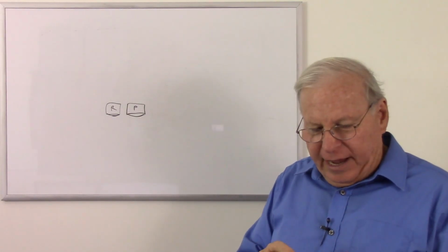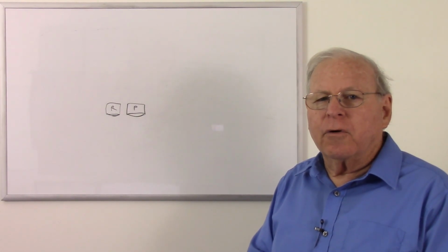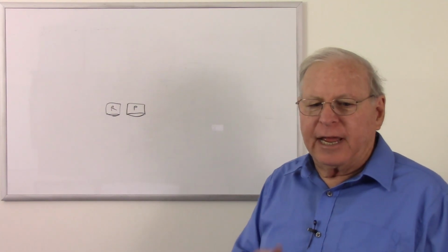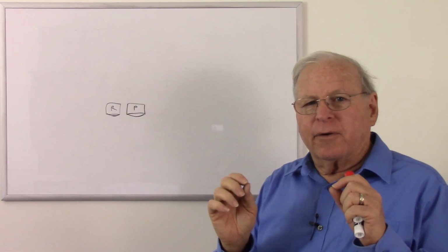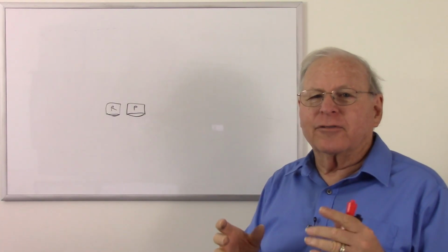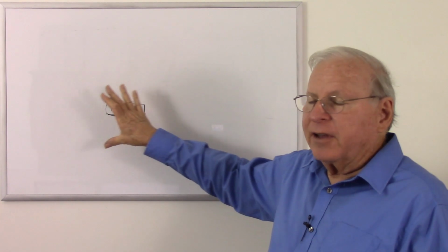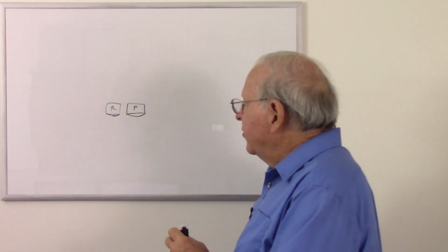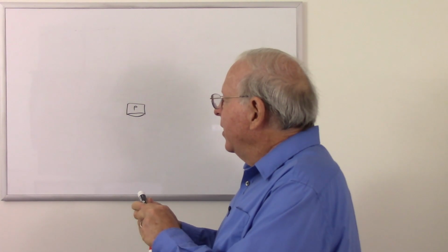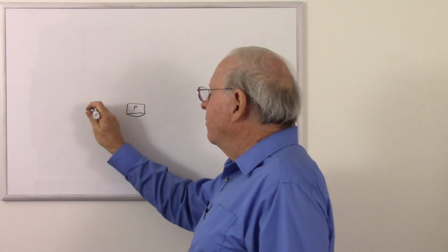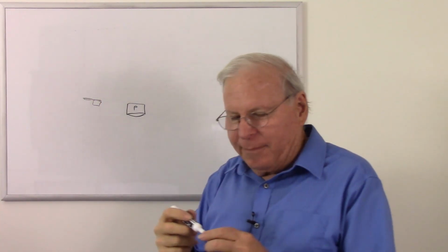Now, what if you have a tape that you are recording over an old recording? Now, the best thing to do would be to take that bulk tape eraser and erase the whole tape. But sometimes you might want to record over just part of it, or just don't have a bulk eraser or whatever. All of your tape decks have an erasing mechanism. The simplest, if we go back to the single head, would be to simply have a little permanent magnet on a little arm that pushed up against the tape when you were recording.